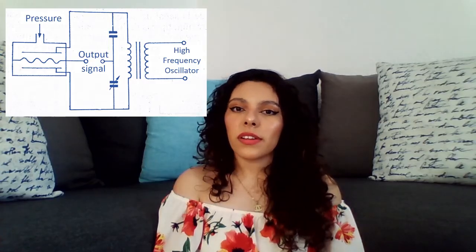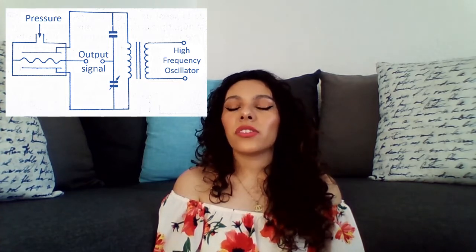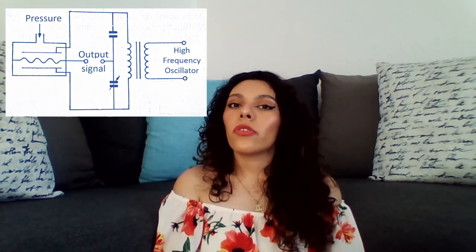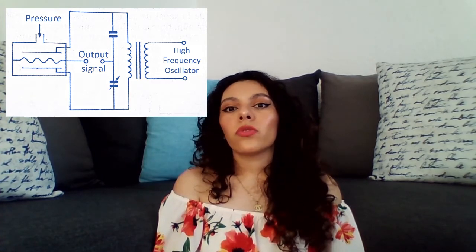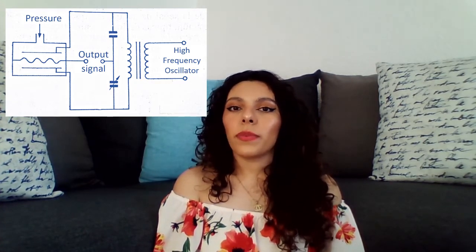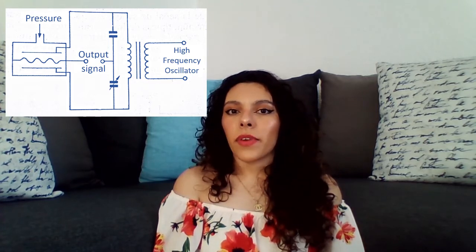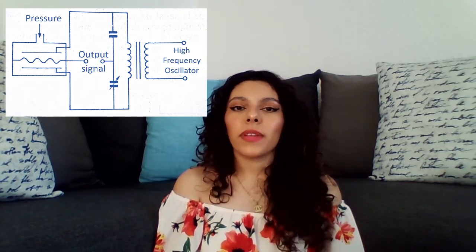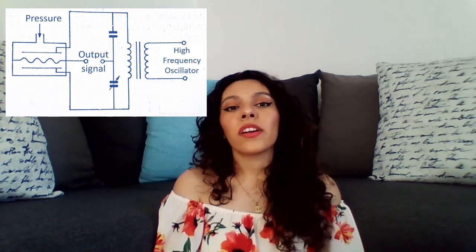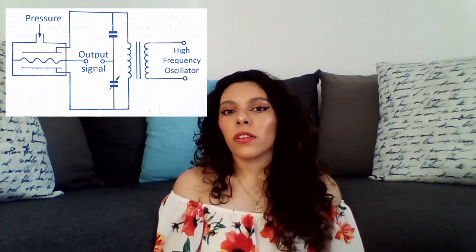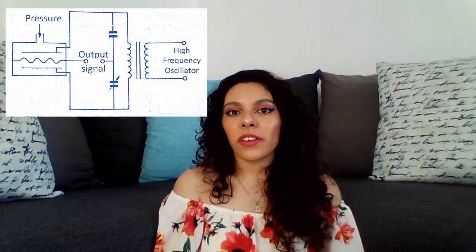Capacitive transducers are based on the variation in capacity that occurs inside a capacitor when one of its plates moves due to the application of pressure. The movable plate is shaped like a diaphragm and is between two fixed plates. Thus, we have a capacitor of fixed capacity and another of variable capacity, which can be compared in oscillating circuits or in Wheatstone bridge circuits.